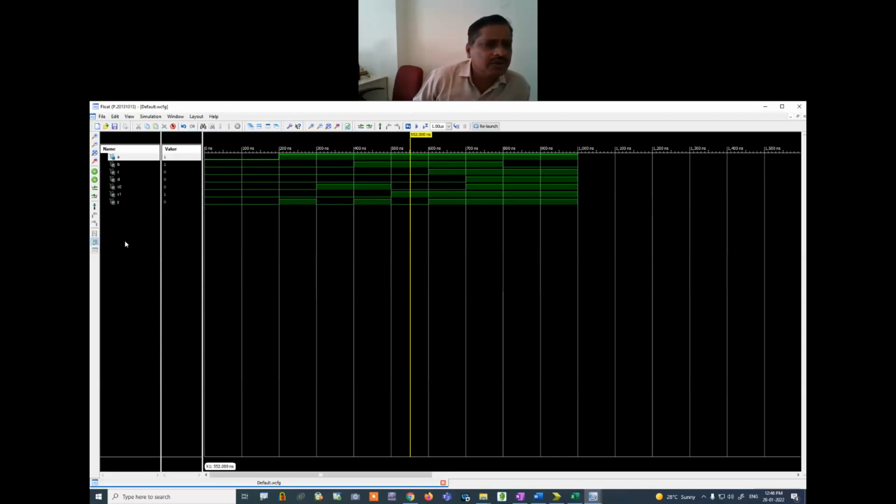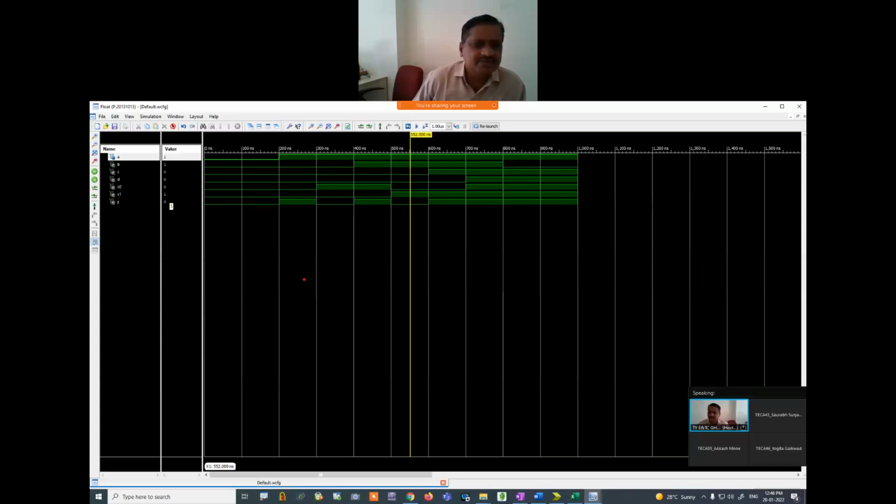Then if I come here, look at S0 and S1. This shows 1 0. S1 is 1. Are you getting me? What is the value of S1? S1 is 1. What is the value of S0? It is 0. So we are getting 1 0. For 1 0, what value should come? For 0 0, A will come, for 0 1, B will come, and for 1 0, what will come? C will come. Is it right? This is 1 0, so for 1 0, C will come. What is the value of C at this instant? The value of C is 0. That's why this Y should be 0. Where is the value of C? The value of C is here. This value of C is 0. That's why the output is also 0.